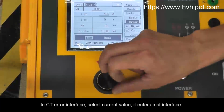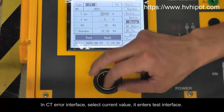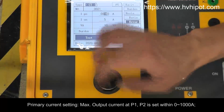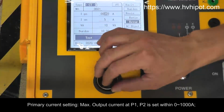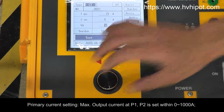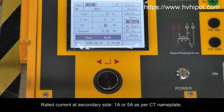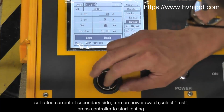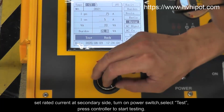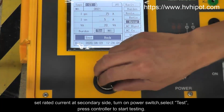In CT ratio interface, select current value, it enters test interface. Primary current setting, max. output current at P1, P2 is set within 0 to 1000 amperes. Rated current at secondary side, 1 ampere or 5 amperes, is per CT nameplate. Set rated current at secondary side, turn on power switch, select Test, press controller to start testing.